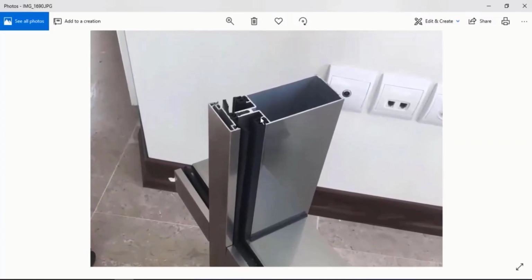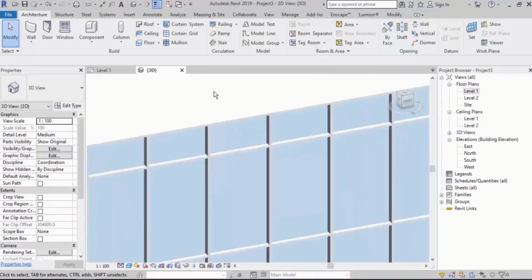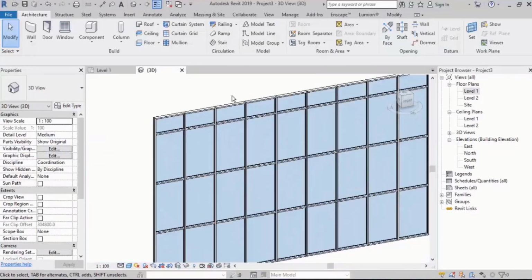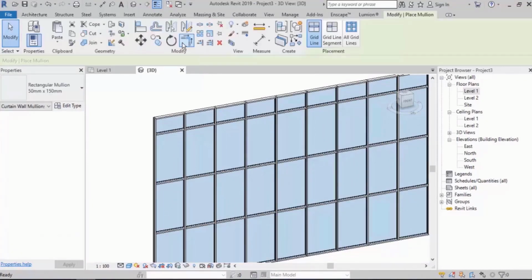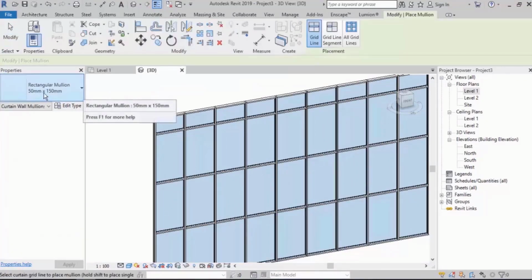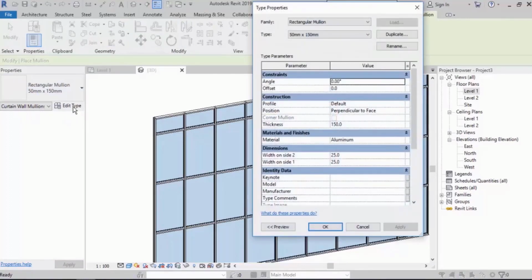Now we want to build a bit simpler one. We don't model these anymore. Well, obviously, for being able to have such a mullion, we need to build the profile too. Let's go and find out. In order to have such a mullion, you need to go to the Architecture tab and select Mullion, and then you can use one of the simple mullions.